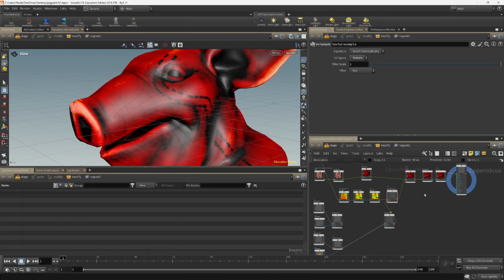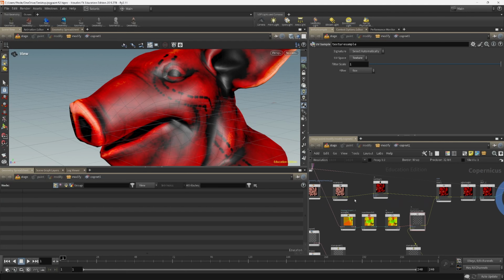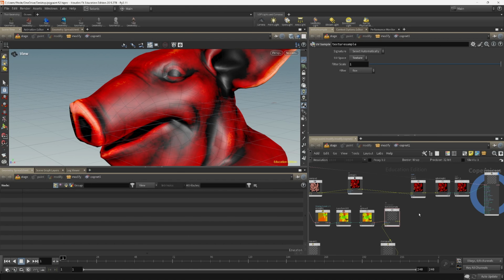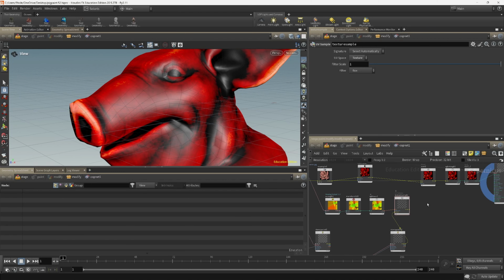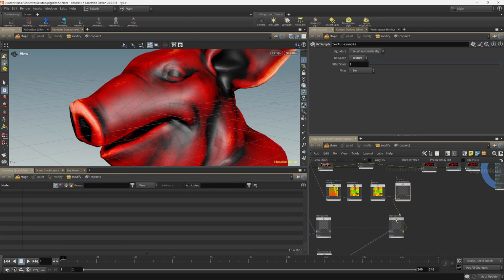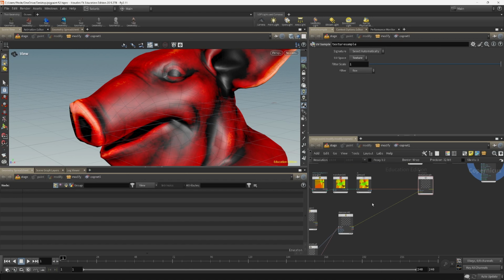Okay, let's use this mat that we made, stamp mat, to affect our texture rather than just slapping it on top. We'll take the original texture and make it the background, and then we'll take this new sort of bloody looking texture and put it on top. And then I want to use this as a mat somehow here. So what I'll do is I could texture sample it all at the end, or anywhere actually. It really doesn't matter where I texture sample this mat.